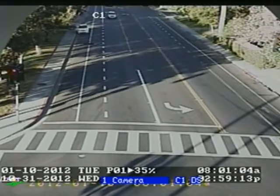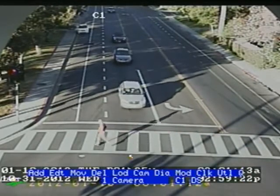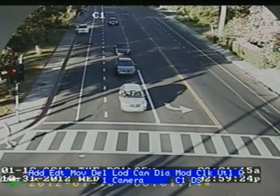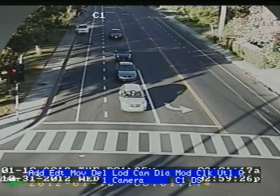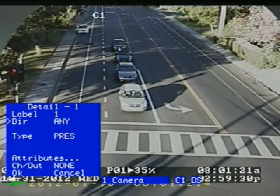I'm going to show you the basics to drawing detection zones. Press and hold in the menu button for 2 seconds on the processor card and release it. The menu will open. Move your cursor to Add. This is where we add the detection zones. Press down or left click your mouse button.